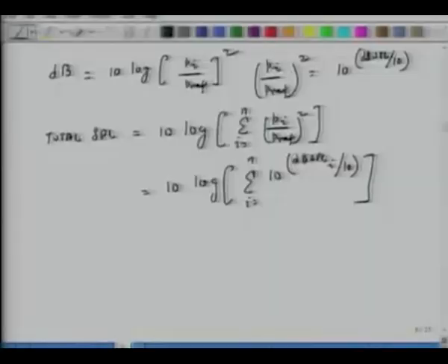Decibel, if you remember our original definition, is a ratio of energies. It's not a ratio of pressures or a ratio of velocities. It's a ratio of energies, or power. And energy is directly proportional to velocity squared, or pressure squared, or displacement squared, and so forth. So when I am adding decibels, I am adding up energies, the total energy. I am not adding up pressures. So eliminating the power and putting it on the other side of the equation will be invalid, because that does not help me add energy levels.